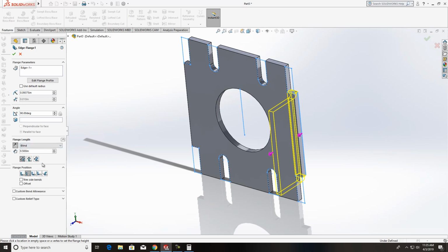And down here, you want to use the outer virtual sharp. You've got the inner virtual sharp, and then you've got the tangent bend. Now that's just measuring it. If you look here, if I hit this one, see how it changes in your drawing. Hit this one. It just changes the way that you're measuring. So we're going to measure from the outer virtual sharp of this. That would be just like where it's intersecting at the bottom of it. And that's what we want.